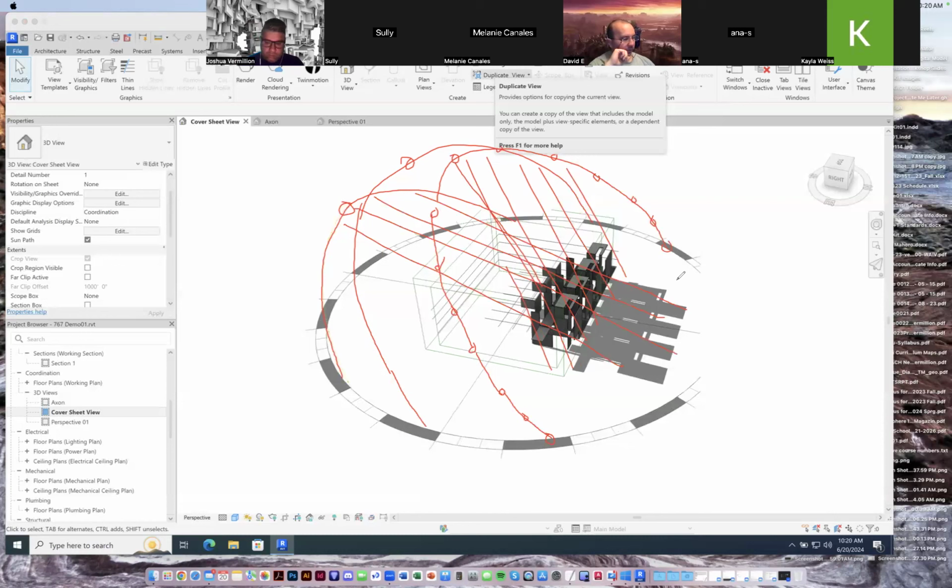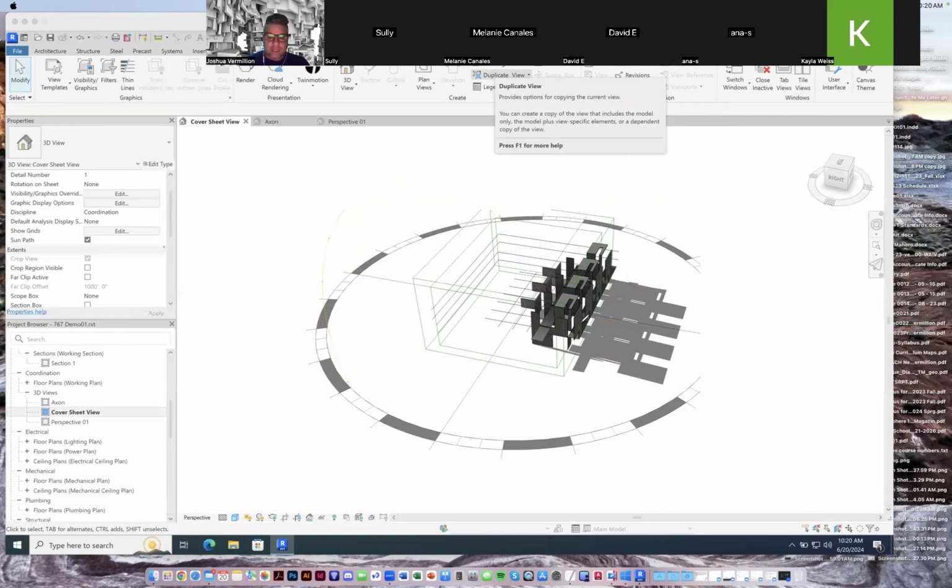All right. So what's nice about this is we don't necessarily have to think this abstractly. What we can do is we can turn on shadows and lights and sun, and then we can get inside and start to see where things are actually shining, where we have shadows, etc. Right? So if we want to align something, let's say a piece of the architecture with casting shadows and light rays through a space, let's say to celebrate the summer solstice, you can turn it on, you can turn it to the right date, turn it to the right time, let's say solar noon on the solstice, and then look and see and start to move things around so you get those alignments just like you want them, right? So that's what I think is very helpful here.